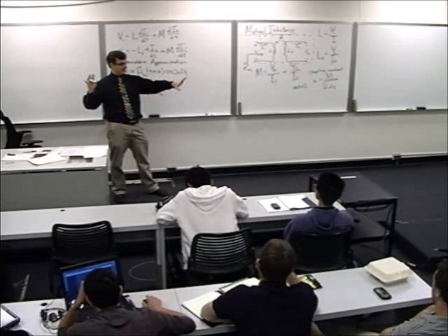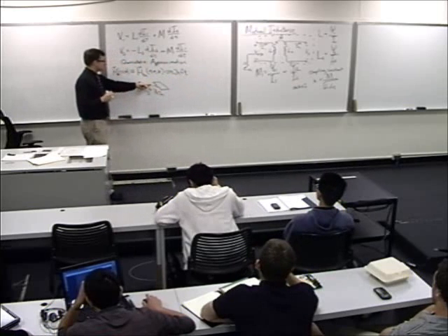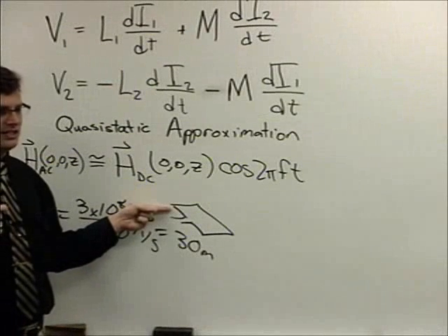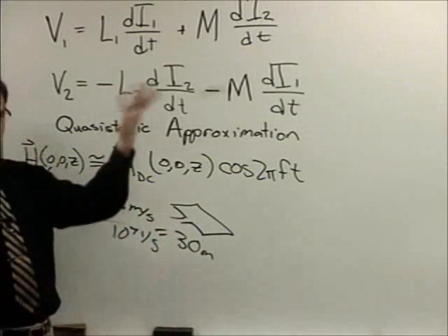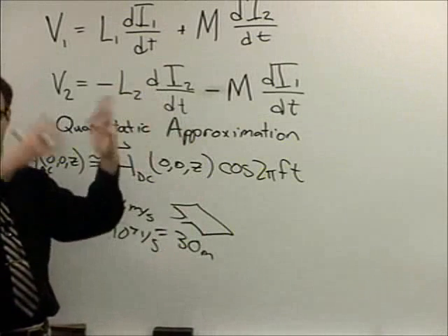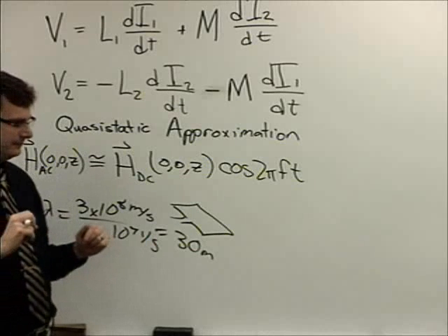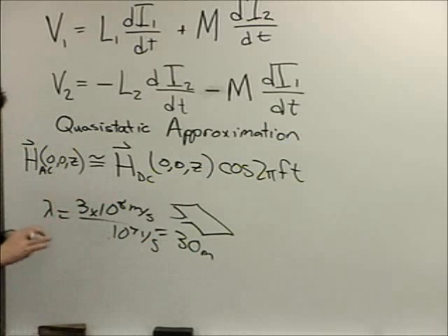But it's not ohmic losses, it's radiated power. In this case, we don't have any radiated power. That's really the assumption that we're doing. And the reason is, this is really just an inductive square. Power is circulating back and forth, sloshing back and forth with the sinusoidal field, but it is not radiating. And that's the key difference.